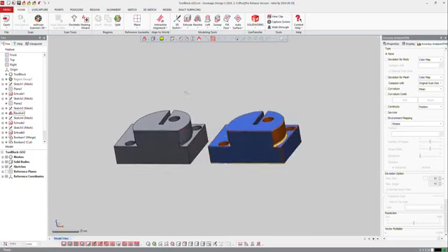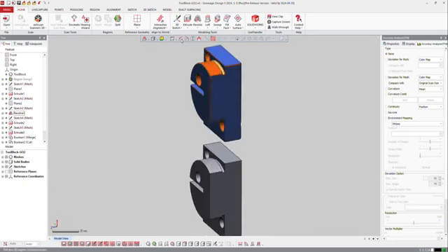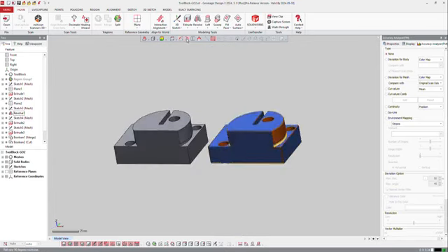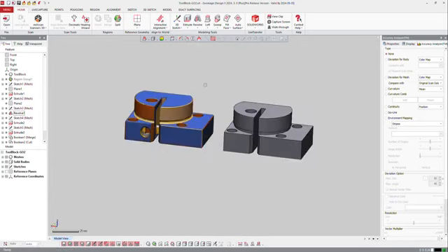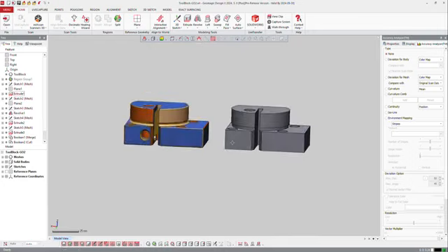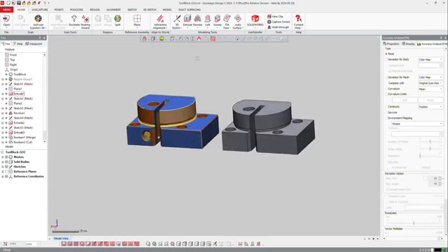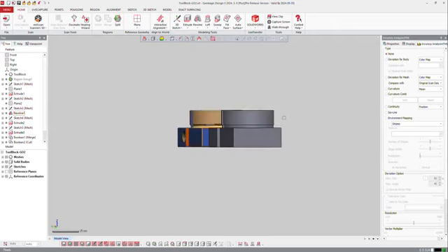When you make a view, afterwards you can turn the view 90 degrees counterclockwise or clockwise here, or flip the view. The other useful feature here is to make it normal to, and just if you didn't select anything before, just click the feature you want to be normal to. If the feature is not planar, you can still use on the cylinder like that, and the software shows you the direction it will use.